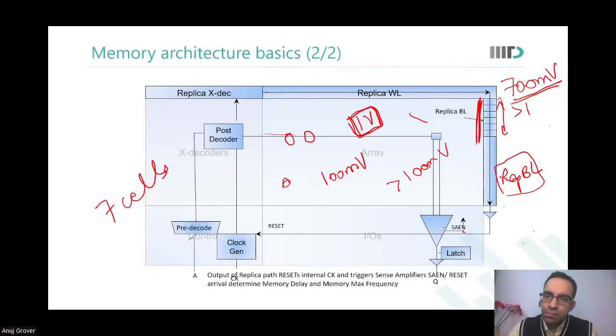Yes, sir. But the bit cell which we use should be the worst case, right? You have to qualify the worst case bit cell. Be careful. We have to qualify the worst case bit cell, but in the replica bit line, many cells would be there and they will be selected in parallel. So you cannot really have the worst case cell there. You just put a replica cell. To take care of the worst case cell, what you may do is tune the inverter at the replica bit line at a still lower voltage, so that you need to discharge still more.